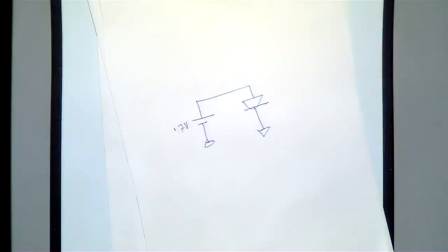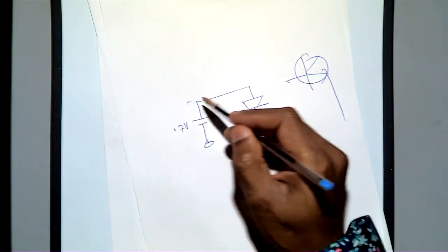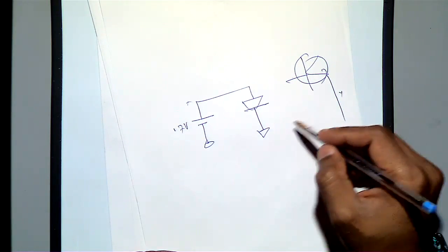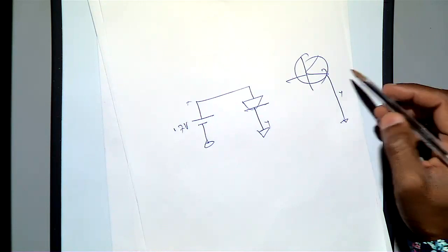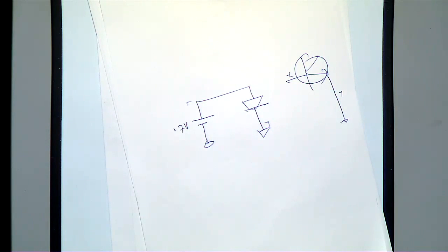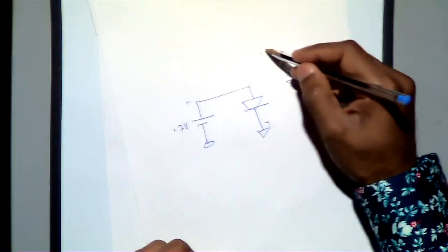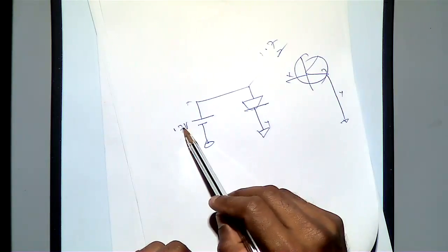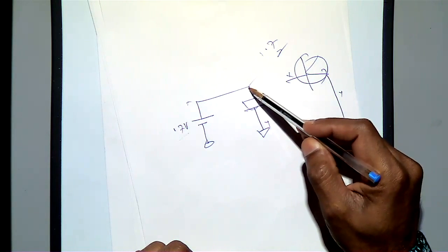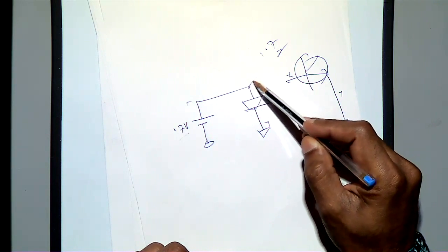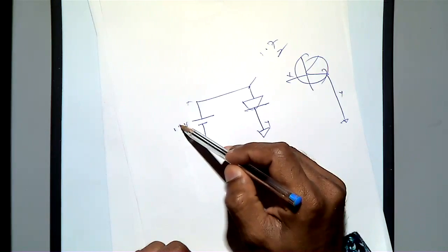So this is kind of the input part of the transistor. Maybe this is X and this is Y. This is just for understanding, an analogy, because I can't use a diode for explaining the transistor. But it will definitely help you understand why we need degeneration. If I put 0.7 volt, what is the voltage here? The forward bias of this diode is around 0.7, so you get 0.7 here.